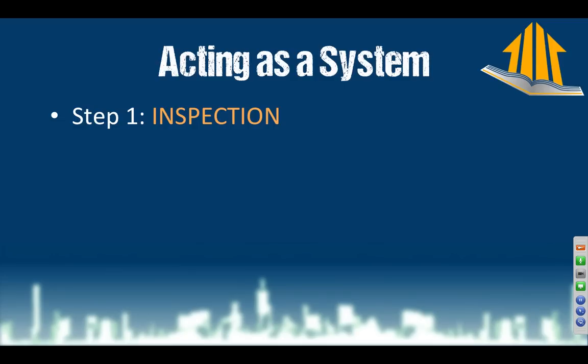Look at both sides of the wall. Look at the inside of the attic. Look at the crawl space and all this stuff, because you want to know what you're dealing with before you start whipping out your diagnostic tools that cost thousands of dollars and making measurements that you don't know what to expect, what they mean, anything like that. Don't test anything until you know what to expect.